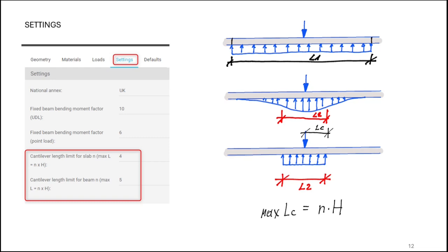However, when our slab or beam is not very stiff and is semi-flexible, the bearing stresses below the element are non-linear, as shown on the second diagram, and we cannot assume that we have UDL stress below the slab.